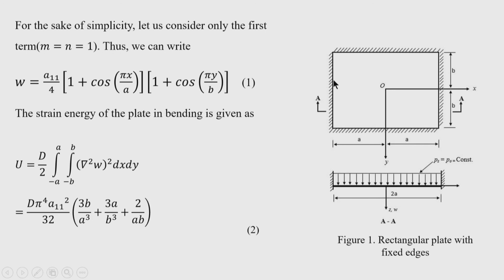Then you can substitute this edge moment in the expression, and then you can find the solution for the plate which has all the edges clamped. So, this contains several steps if you adopt Levy's method, and the expression will be very lengthy.